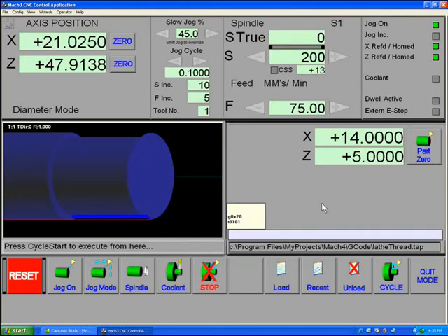It is possible to select offsets from other tool entries using any tool. So you could, for example, type T0105, which means use the offset from tool number 5, but use the other dimensions of tool number 1. That's an advanced usage, however, and for most new beginning users, and who else will be watching this video, you'll be using normally T0101 or T0202. So you're basically going to be duplicating the first two numbers on the second two numbers.